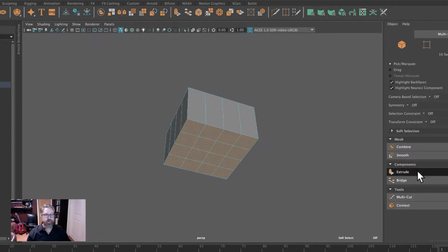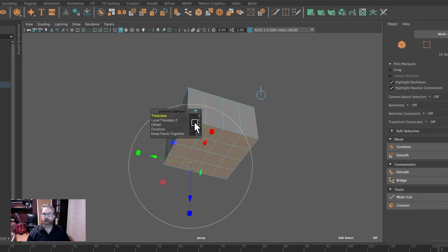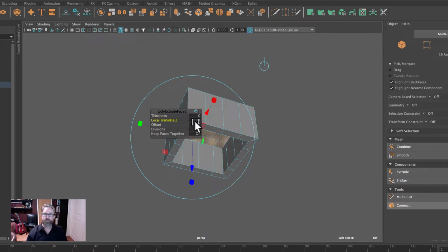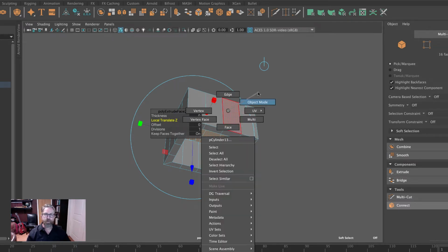We'll come to extrude, and our offset, you'll recall, is 0.8. And we extrude a second time. And our local Z is -4. So just a real quick 2-step process to give us the 2x2 brick recessed unbeveled version. And that's why we didn't have to save it, because it's just this quick to create one.